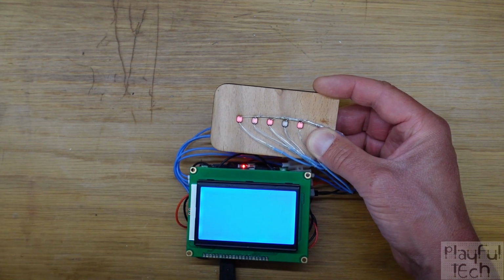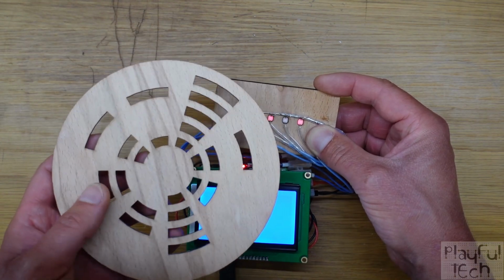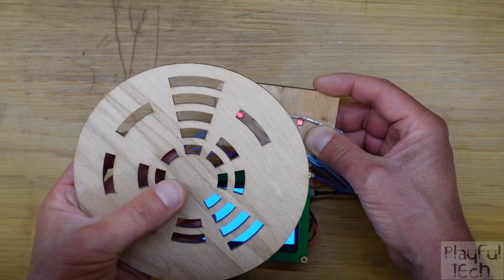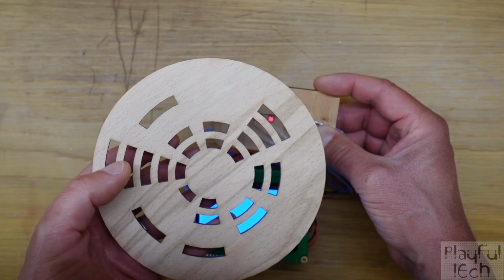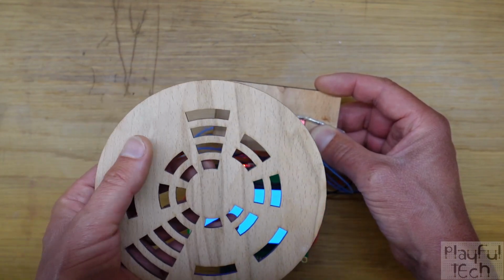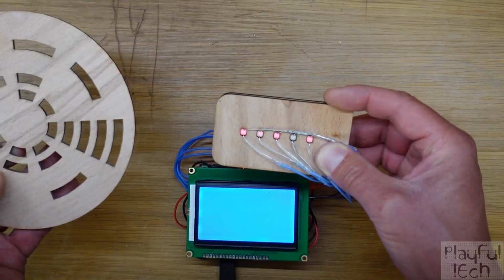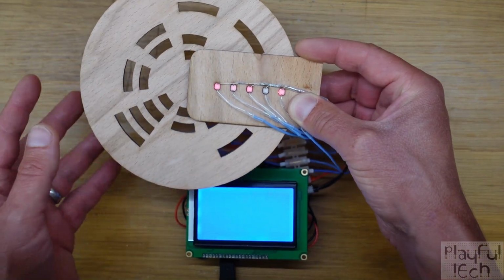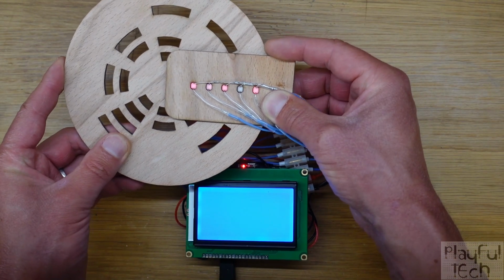of encoding just a single character value on the card, I've made a wheel that encodes an entire message. So around this wheel there are 8 sectors, and each of those sectors has 5 different segments that can either be cut out or filled in solid, which again correspond to the 1 and 0 values of a 5-bit binary code. Now if I insert the wheel into the reader here, and then as I rotate it clockwise, I want you to look at the output from the LCD display there.